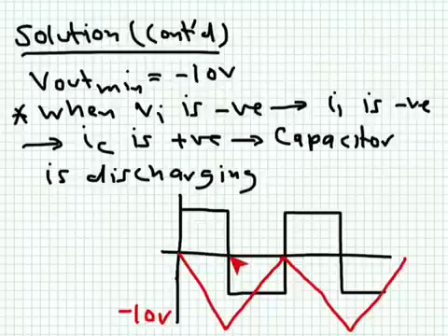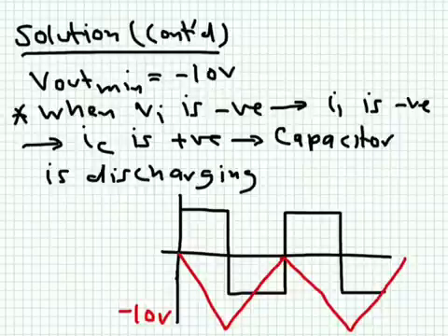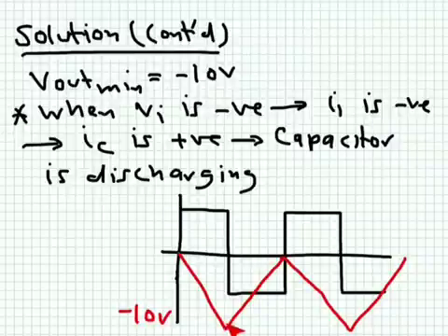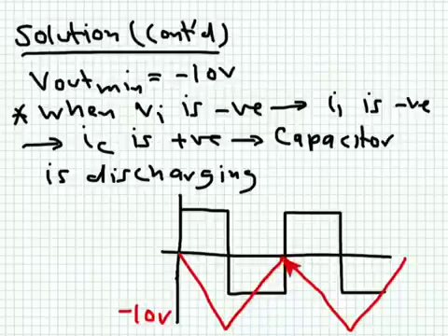Now when we repeat the cycle again, so we apply the negative voltage, the current will flow in the opposite direction, and then you can show very easily that the capacitor will start to lose its charge, and because it charged linearly through the first 10 milliseconds, it discharges linearly also through the other 10 milliseconds, so it will go to zero again.